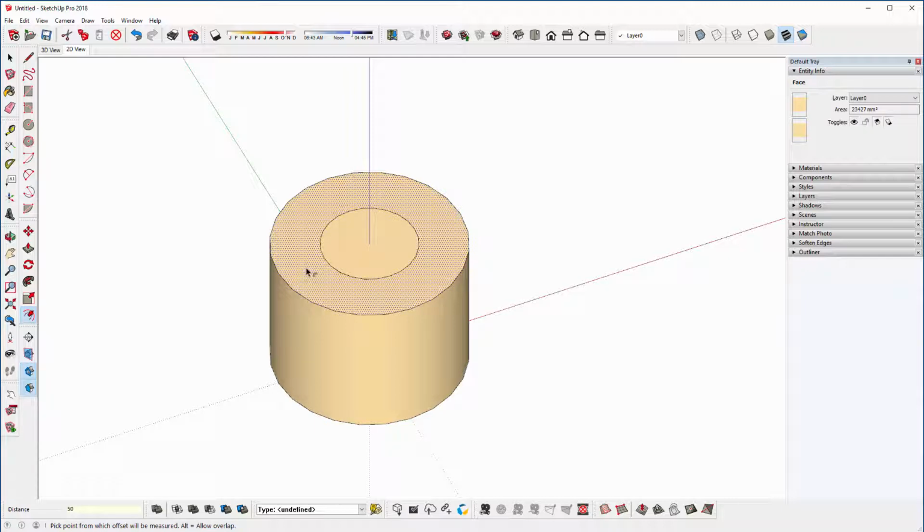and if 50 was too much, you could just type 25, enter. As long as you're still in the same tool, you could keep repeating different measurements until you change tools. So I'm just still typing different measurements, and let's finally decide on 30 millimeters in.